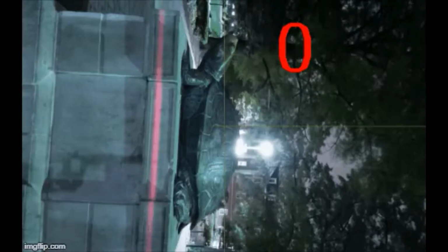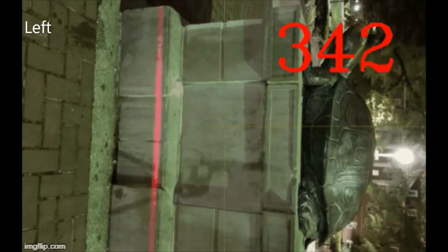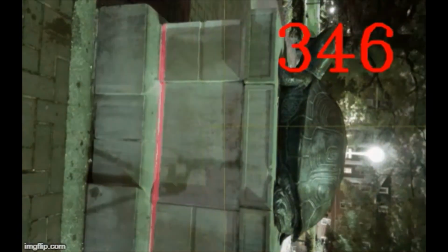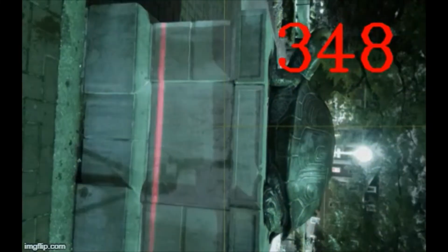After my system was calibrated, I went to my target, Testudo, to begin data collection. I decided to take separate data sets from 4 sides of Testudo, normal to each face of the concrete base. On each side, I took about 30 photos since I wanted my point cloud to be as dense as possible.